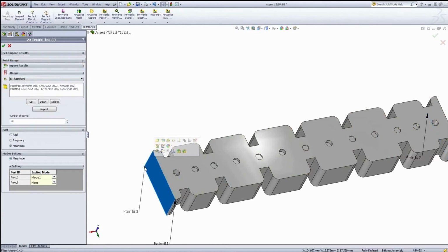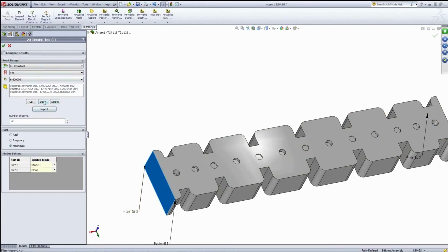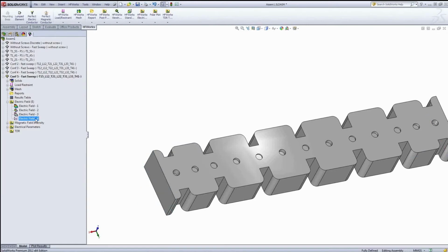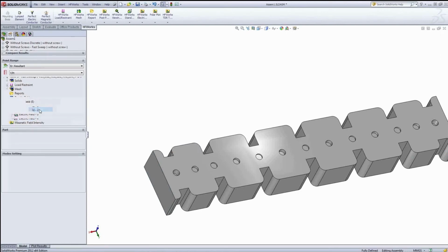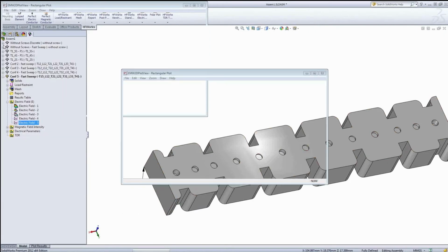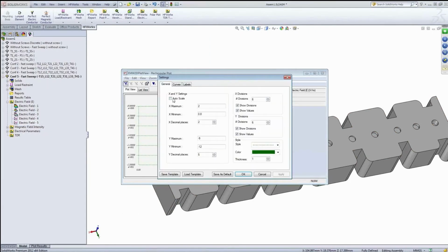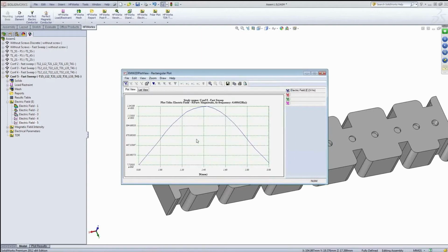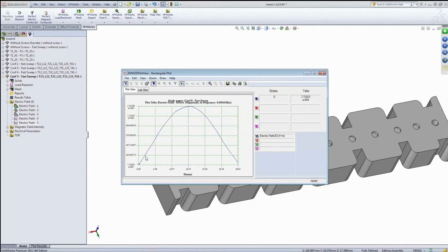Okay, so maybe I don't know if you can do this. So I have to here with this selection. Between this point and hopefully this point. Hopefully we can take these 2 points. And then if I just click here and auto scale this, that's my field. And then I can probe this field point by point through that section. That's what my field is doing. I expect that it's basically the TE10 mode. So I can look at that data.